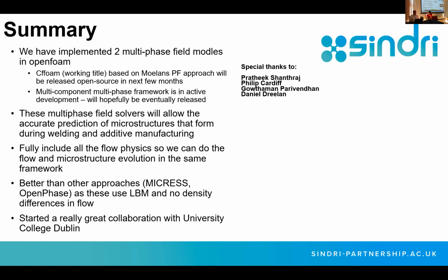Yeah. So at the moment there are n minus 1 solid phases and 1 fluid phase, and then whether it's fluid or not is basically determined by a multi-component volume of fluid type approach. I don't know if it's normal, but that's what I've added to the Mule's solver. To make it fully thermodynamically consistent, the next thing to do is to make it n-2 solid phases, 1 liquid phase and 1 gaseous phase. Then we can fully couple to the Gibbs free energies for every phase.